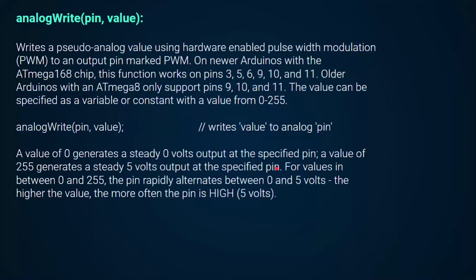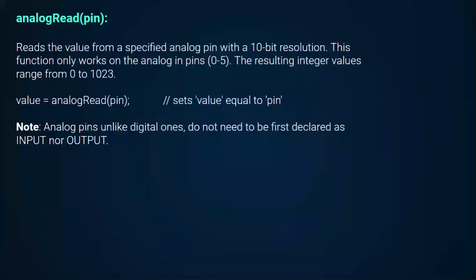And what does that 10-bit resolution actually mean? Is it the size? Yes, it is the size. So what can a bit represent? Zero and one. So one bit can represent 0 and 1. How many values can 2 bits represent? Four combinations, 2 to the power 2. How many can 3 bits represent? 8, 2 to the power 3. So now calculate 2 to the power 10. 1024. Correct. So from 0 to 1023. All good? Yes, understood.